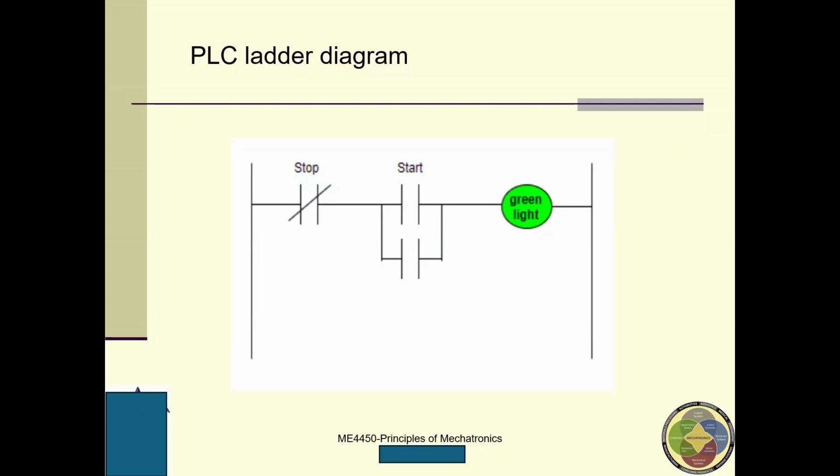As I said, because in this convention, in the PLC world and in the control relay world, the stop button is manufactured differently. The stop button is always normally closed until you press it, then it will be open. Open means forced: the water cannot flow. You understand, guys?